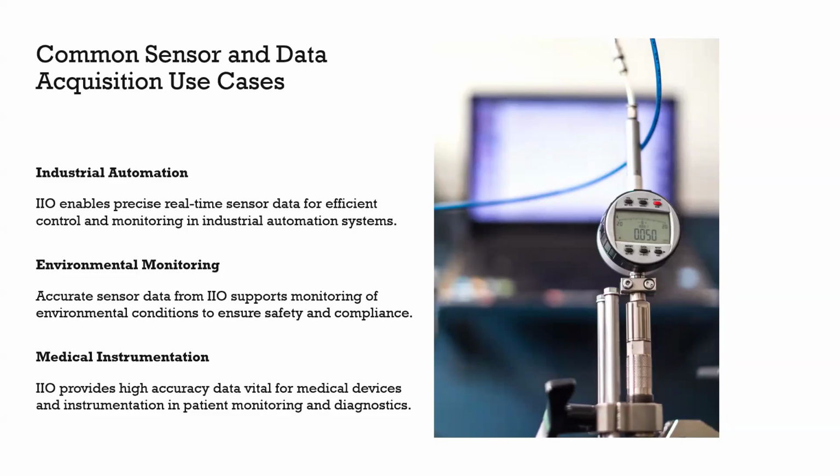The character drivers used to have one more advantage earlier. For any high-speed data streaming, the application used to use the character drivers. But IIO devices were used only for low-speed data and only for configurations. This used to happen earlier, before kernel version 6.